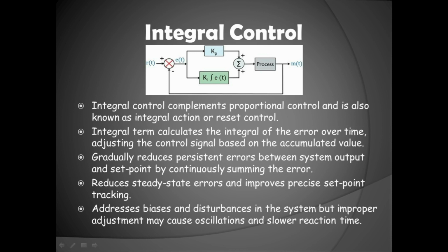So what does integral control really do? Integral control introduces time into the equation. So unlike in proportional control, where the controller is responding to the value of the error, in integral control, it is also reacting to the value of the error over time. Meaning, even if the value of the error is consistent, the system output will continue to increase as long as the value of the error isn't decreasing.